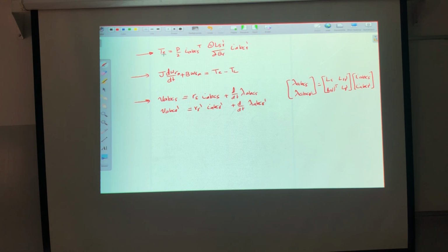This one? Simply we stated that if I need to find the torque, I need to do either minus partial W_f by partial theta, or I need to do partial W_c by partial theta. And we stated for a linear magnetic circuit, W_f equals W_c. Now this one, we said, is the field energy. It has a physical meaning.